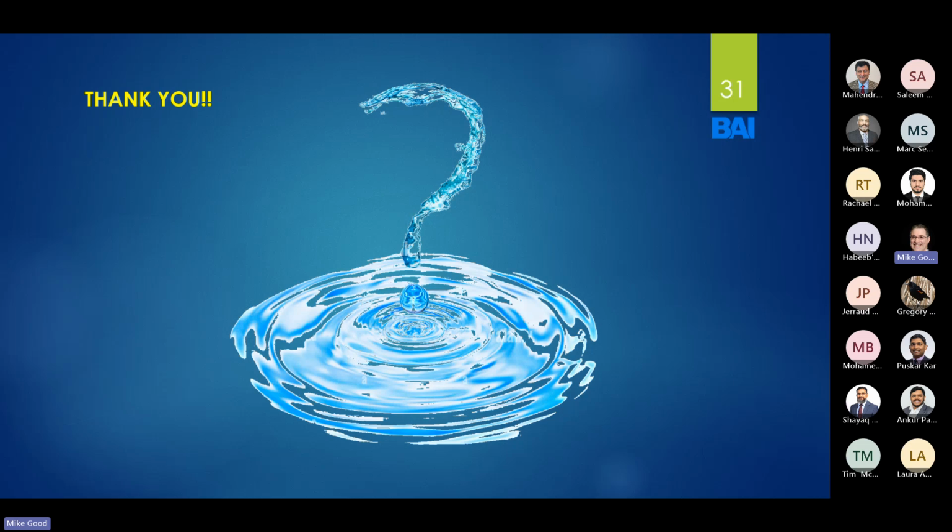And so we want to prevent these bridges from getting scoured away. On the structural side, when we do inspections, one of the things we're always looking at is, is part of the foundation visible? Has it been undermined at all? What's happening behind the abutment? Is there any piping going on where water is going behind it? We see that quite a bit on culverts, where the water is working its way around the culvert instead of through it. So we're always on guard for those kinds of issues when we look at bridges. We might not be experts on the numbers of how it got that way, but we can certainly see what the likely cause is and how it may have occurred.